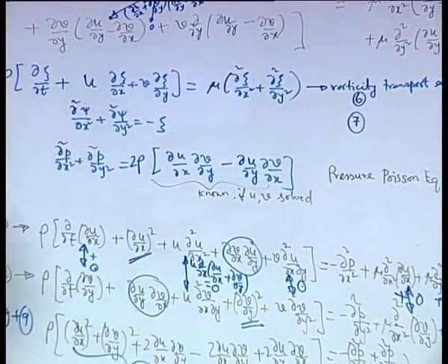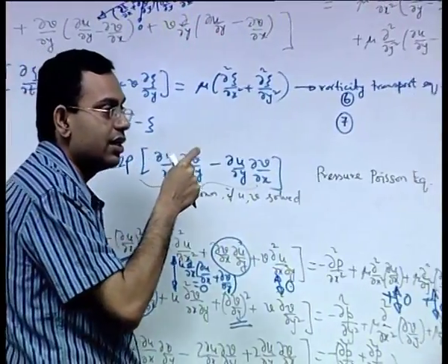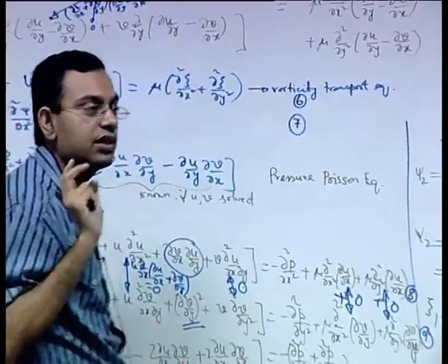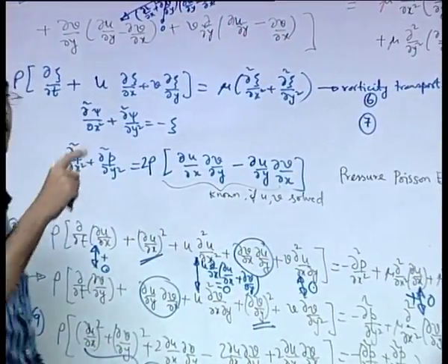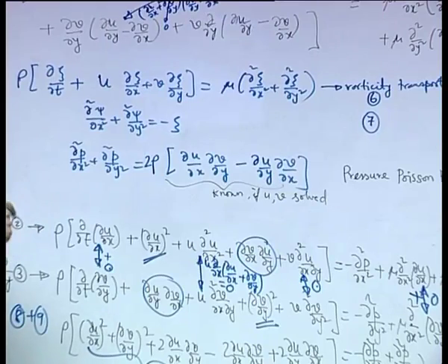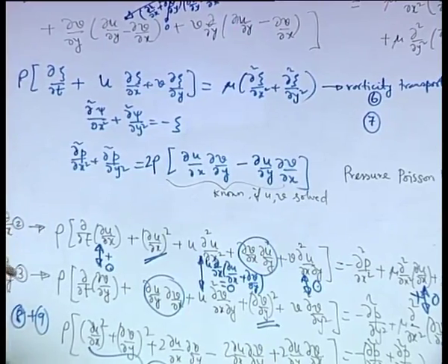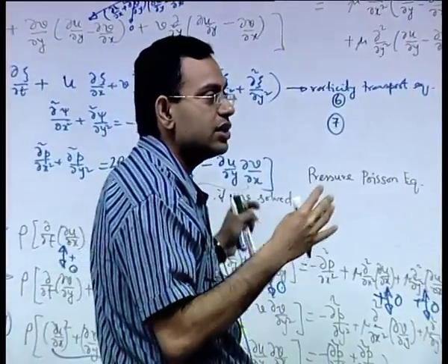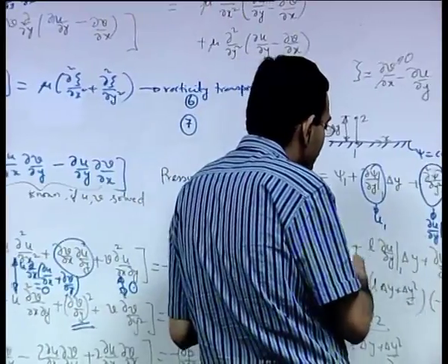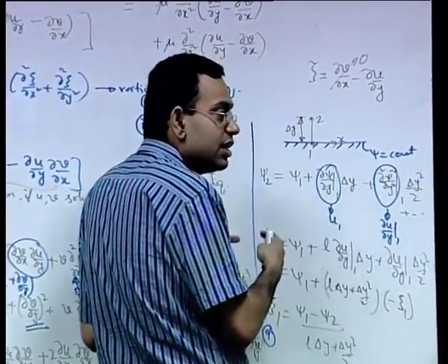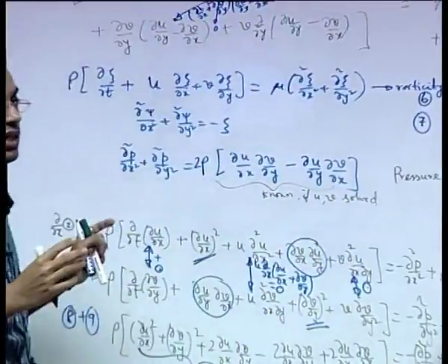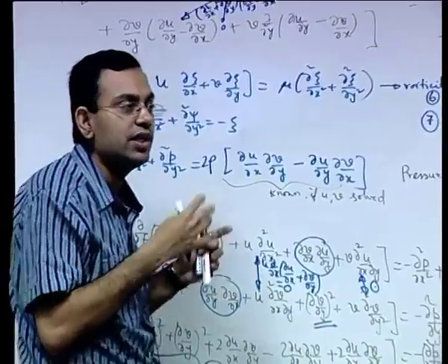See, if you are very careful, you have seen that very deliberately we have worked out this particular method by considering a special case of a 2-dimensional problem. The reason is that the stream function is defined in this way for a 2-dimensional problem. So, you cannot easily extend this concept to a 3-dimensional problem. So, this puts a lot of restriction on the solution methodology. Not only you lose track of pressure, you introduce artificial boundary conditions for vorticity, these are still peripheral points, but to me the most important restriction is that it is not generally applicable to a 3-dimensional problem.